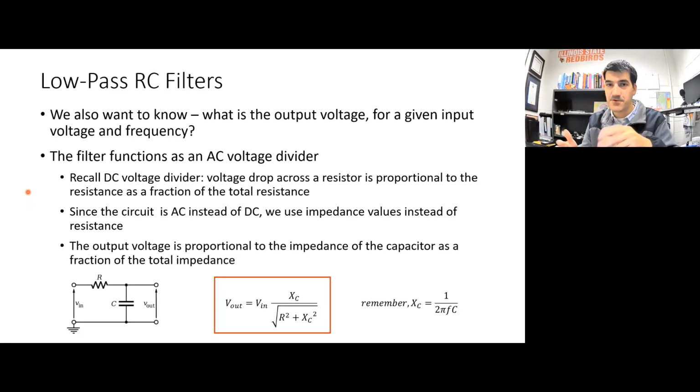All right, if you remember the voltage divider, that's super easy because all you have to do is take the resistance of that resistor as a fraction of the total resistance. R1 plus R2 is 4 ohms plus 6 ohms, which is 10 ohms. And if we want to know the voltage drop across resistor 1, then we take 4/10 of the input voltage.